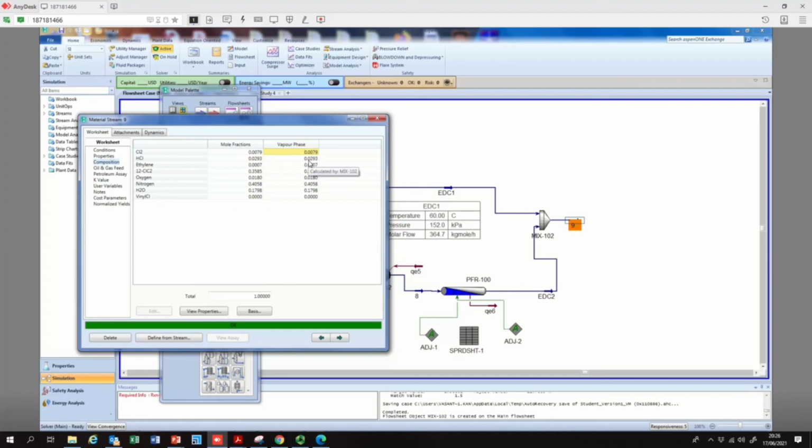We need to get 99.5% pure ethylene dichloride in order to avoid coking in the pyrolysis chamber. Also remember, water will form an azeotrope with hydrocarbons like ethylene, which means it will become very difficult to separate.